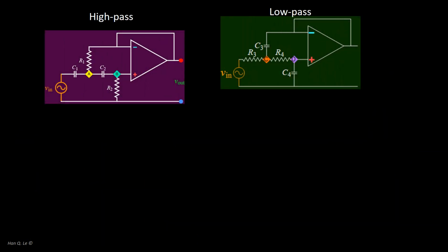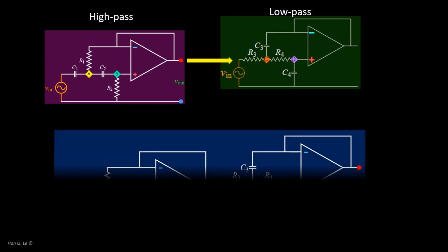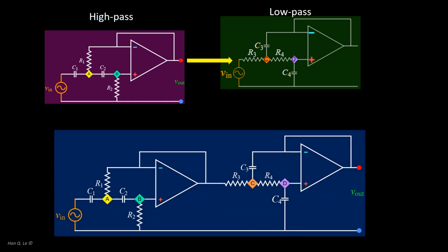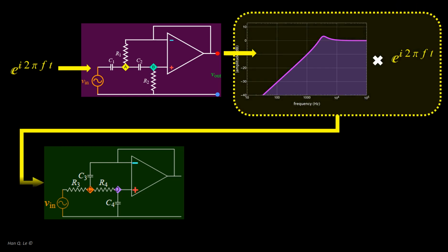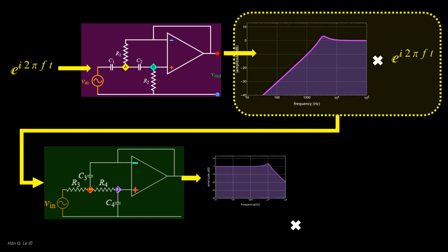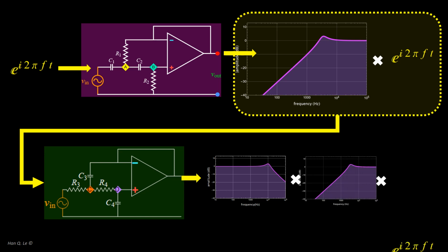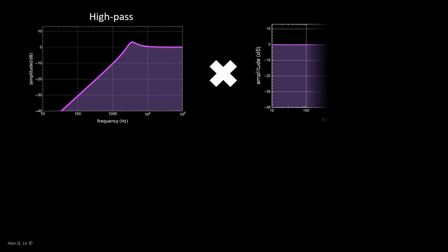Both filters, high-pass and low-pass, are needed to reduce both noises and interferences. Connected together, they form a bandpass filter. Obtaining the response function of the combined circuit is quite straightforward. It is the product of the two response functions. On the log scale, a product becomes a summation.